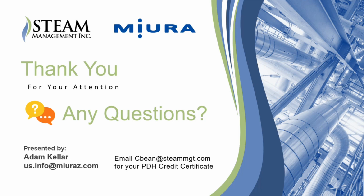Somebody asked whether water purity is more critical for Miura boilers compared to others. Is that true, and why? I would say it's sort of not. The water treatment requirements for all boilers are basically the same, based on ABMA, and we use the same water treatment recommendations that every other boiler manufacturer does.